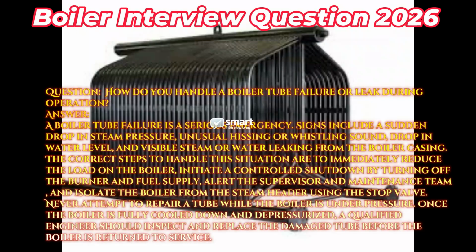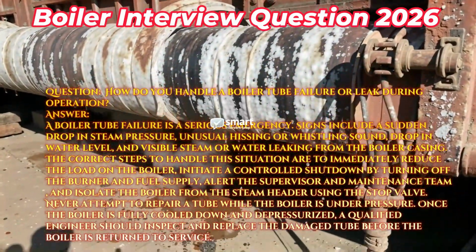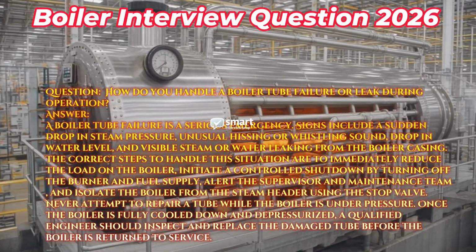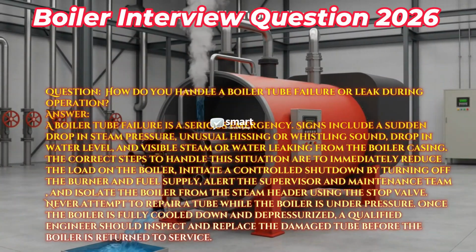The correct steps to handle this situation are to immediately reduce the load on the boiler, initiate a controlled shutdown by turning off the burner and fuel supply, alert the supervisor and maintenance team, and isolate the boiler from the steam header using the stop valve. Never attempt to repair a tube while the boiler is under pressure.